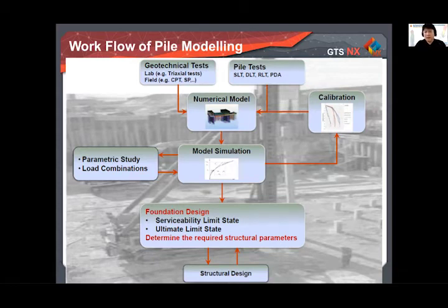And you run your simulation, and you will get results in terms of deformation, stress and strain forces in the piles. You can also run a parametric study, varying the layout of the piles, the diameter and the length as well, and also different load combinations, such as structural load, wind load, earthquake load, and combinations of these.